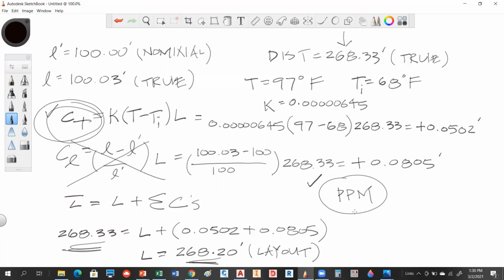Yeah, like where you set it, but also how it settles and the temperature. Well, the prism actually has what's called an offset associated with it. So if you look at the cross section through a prism, when the light strikes through that glass, it comes in and then it bends like this and then it comes back to the EDM. So they set the prism center with what's called a prism offset so that that distance is exact.